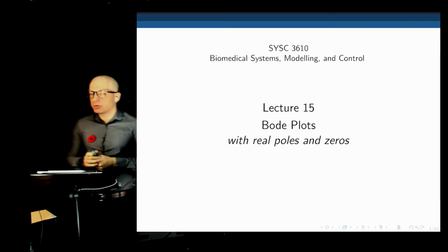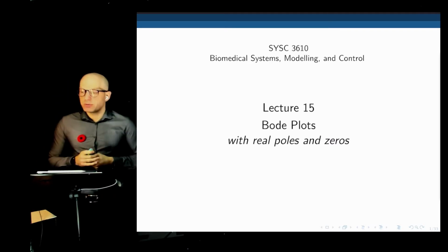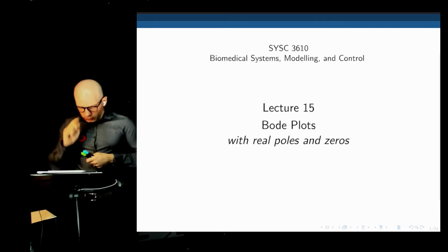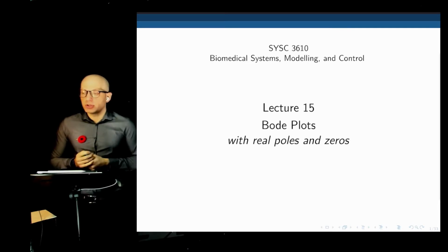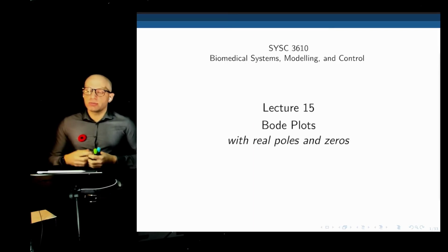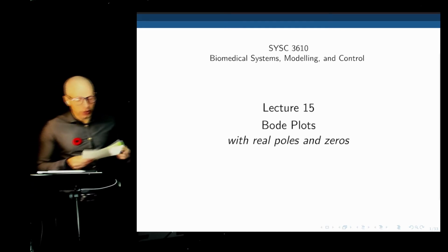One main application of Bode plots is that by taking the Bode plot of a system, if you can define that experimentally, we can infer the transfer function of the system just based on the Bode plot. There are a lot of real applications of this. For example, when you buy a component for your electronic system or for a mechanical system, you're probably interested in looking at the Bode plot to see up to which frequency that specific component is recommended. When you buy any electronic components, you'll see a Bode plot of that component there. So we'll see how to read and how to create one.